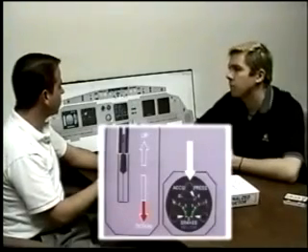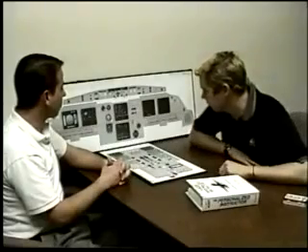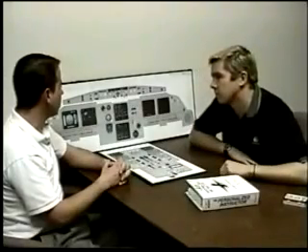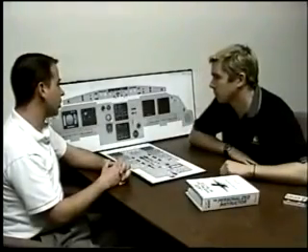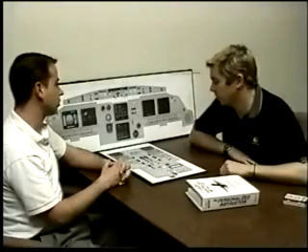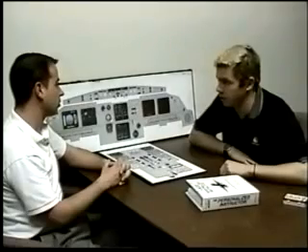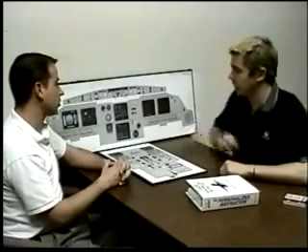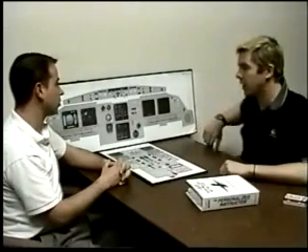Let's start with push back. You set the parking brake, tow bar is disconnected, and the airplane starts to move. How might you stop the airplane? Well, if the parking brake switch is set, the tow brakes are basically deactivated. So I have to release the parking brake handle and then try to get on the normal brakes.